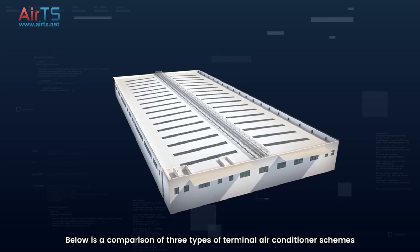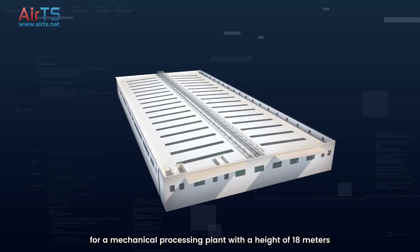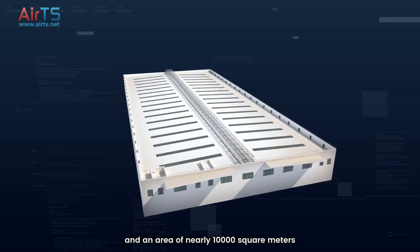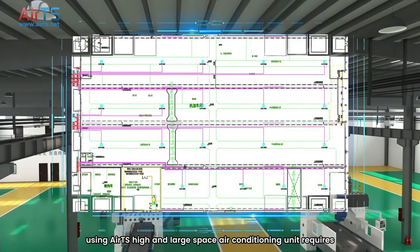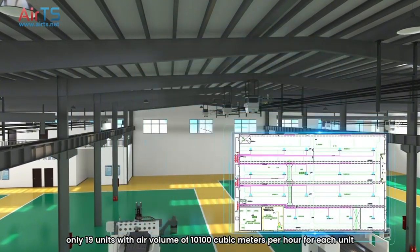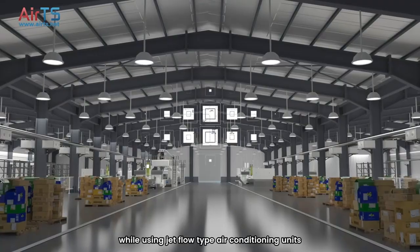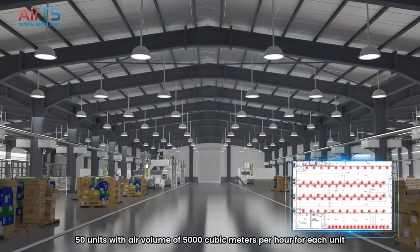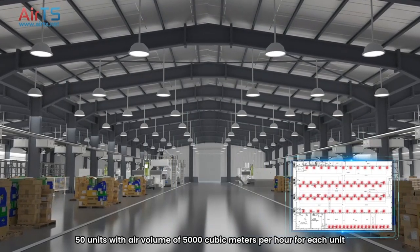Below is a comparison of three types of terminal air conditioner schemes for a mechanical processing plant with a height of 18 meters and an area of nearly 10,000 square meters. Using AirTS high and large space air conditioning unit requires only 19 units with air volume of 10,100 cubic meters per hour for each unit, while using jet flow type air conditioning units to achieve uniform temperature effects requires 50 units with air volume of 5,000 cubic meters per hour for each unit.